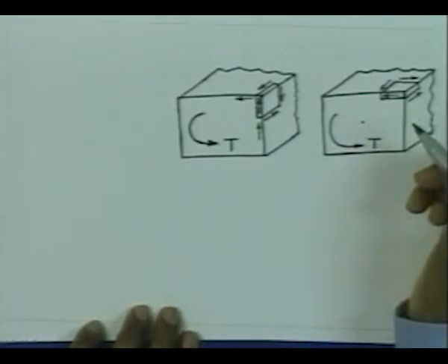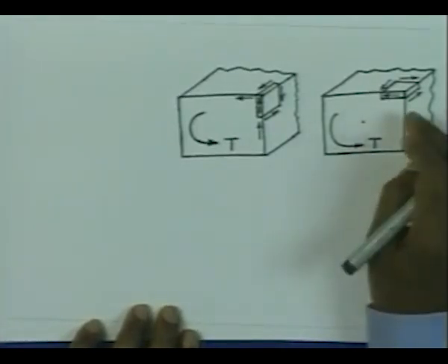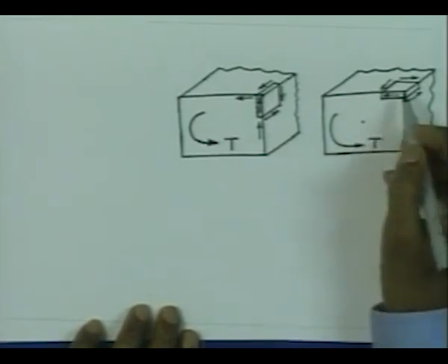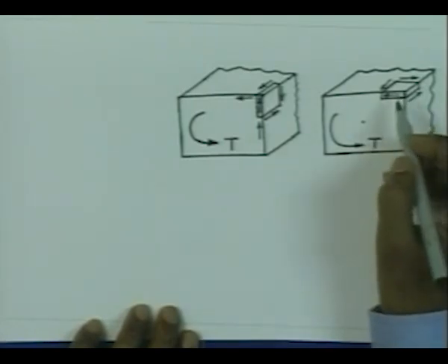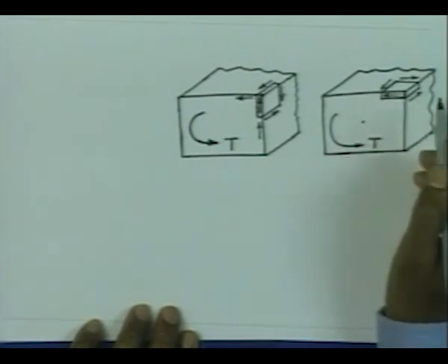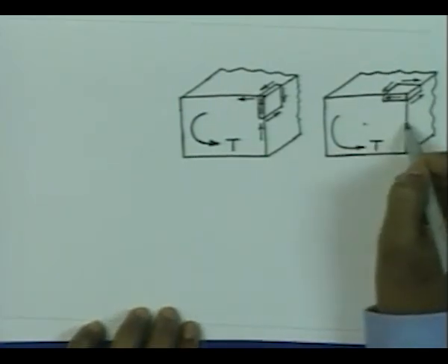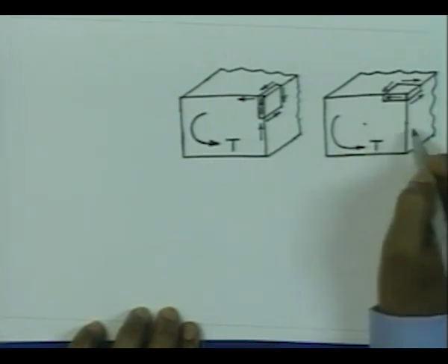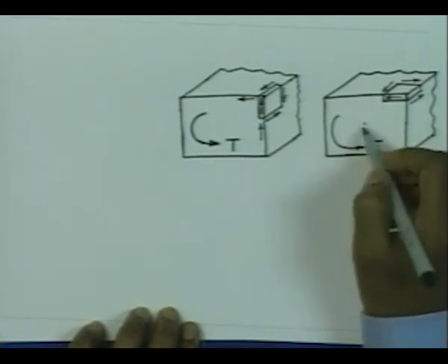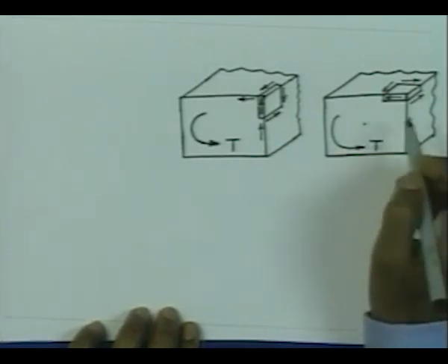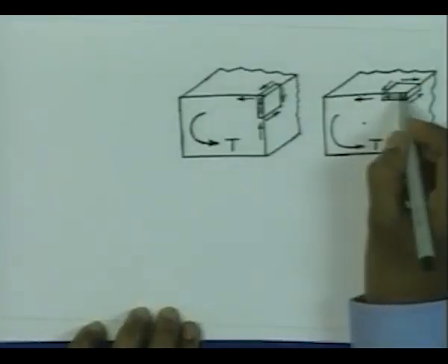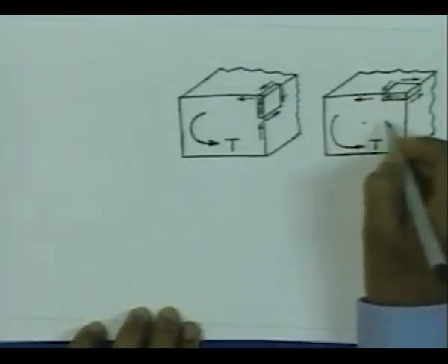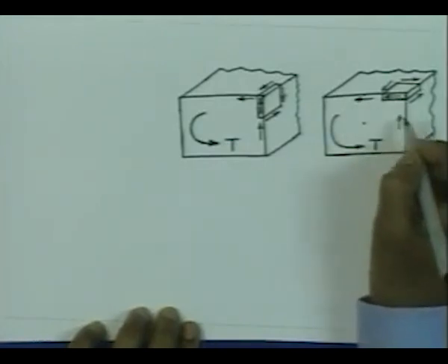In the case of the circular shaft, we have found that the stress is going to be maximum at the furthest point, but in such cross sections it is different. The stress at the furthest point, if it is a corner, is 0, and if it is a point somewhere here, the stress is maximum, but then high stress occurs at a point which is not the furthest. It can be at a point here which is at a distance shorter than this distance. So, the stress acting parallel to this boundary, if this is a longer side than this one, is going to be higher than the stress acting at this point.